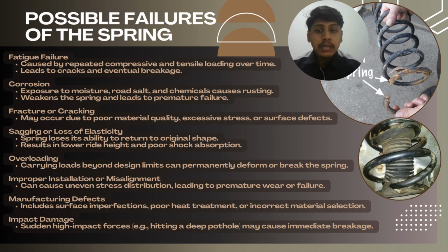Next is improper installation or misalignment. It can cause uneven stress distribution, leading to premature wear or failure. Next will be manufacturing defects. This includes surface imperfections, poor heat treatment, or incorrect material selection. And the final one will be impact damage. It is due to high impact forces, for example, hitting a deep pothole may cause immediate breakage.